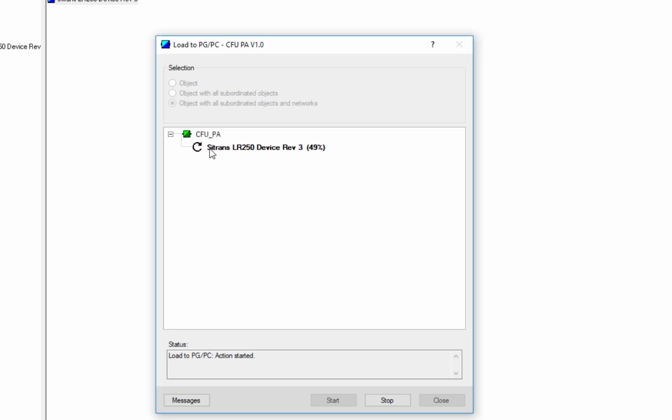If you've ever used PDM before on Profibus PA, please note the speed that this is uploading. It's vastly faster than a standard Profibus DP to PA connection, so it can help with your commissioning times.